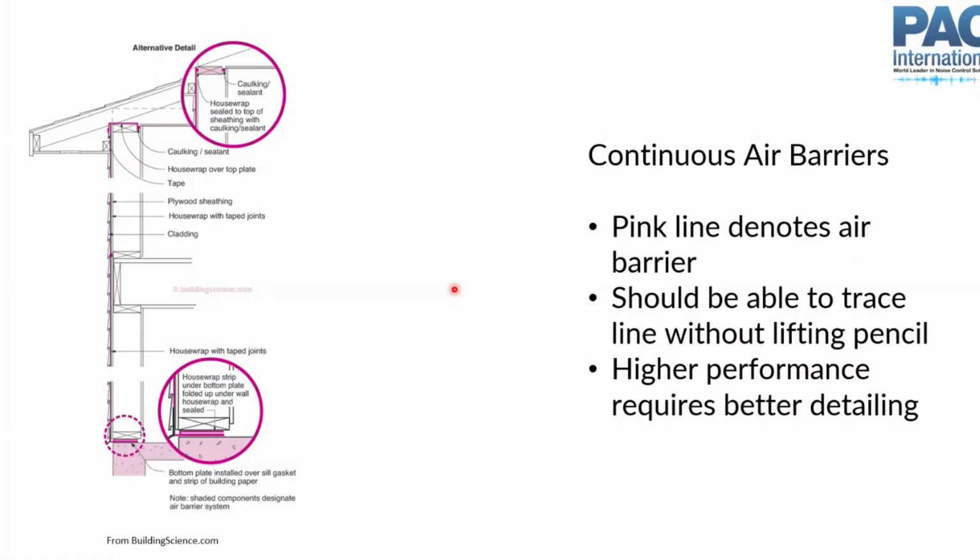When we're talking about the cavity path in acoustics, I think the way to think about it is you want a continuous mass layer. And that could be, it's often drywall for walls. Could be CMU block or concrete or mass timber, but you want this continuous mass layer. And so anytime you have an interruption in that, you need to figure out how to seal it some way. And ideally, you want that seal to at least be somewhat close to the mass of this other continuous mass layer. And so you can think about that like a continuous air barrier.